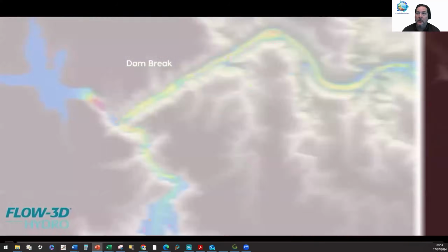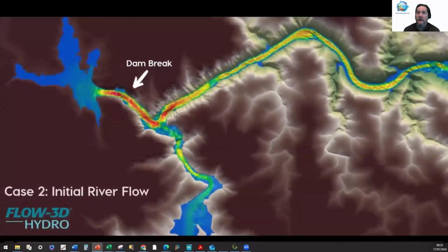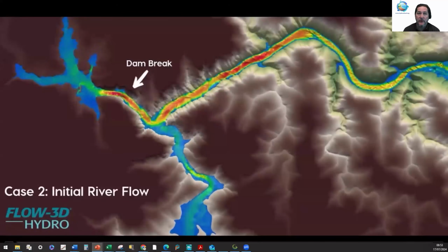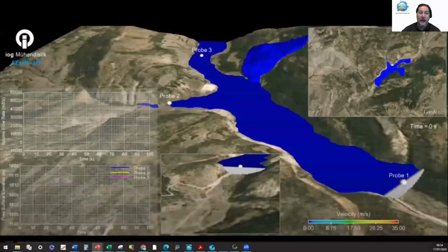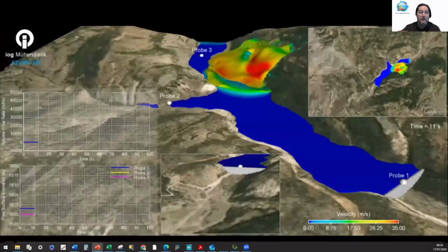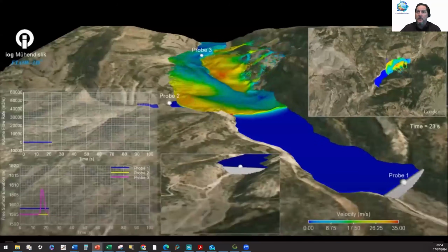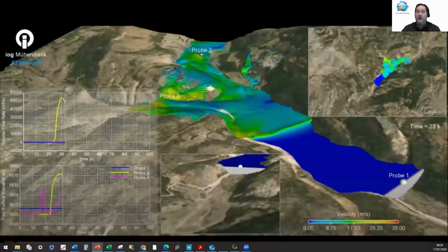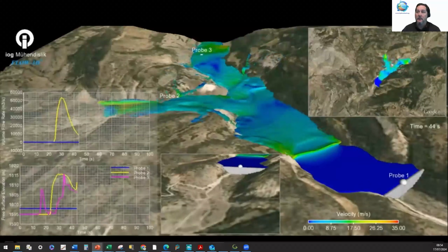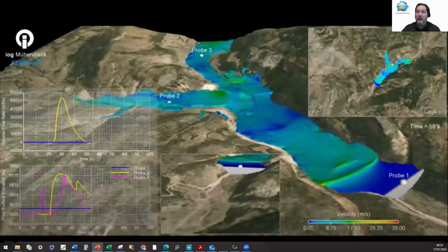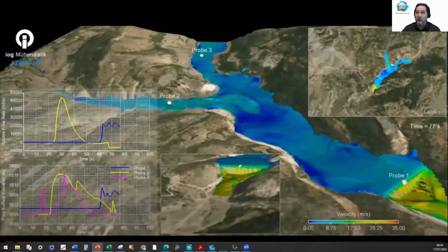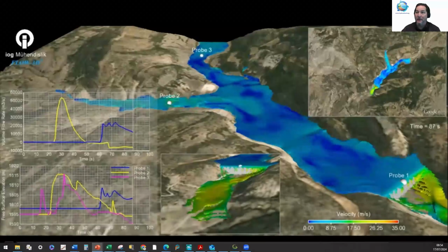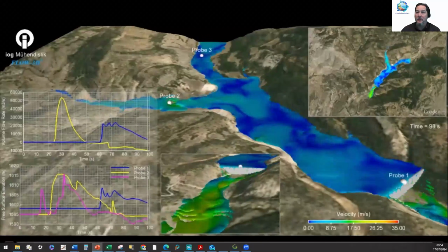So it's getting to be a little different than some of the previous advice, which you might still see published out there, saying, oh, you can only use 3D at the actual structure, and then you'll have to couple it with 1D or 2D anywhere beyond the immediate range of it. Computational power, software and hardware abilities have been increasing, and it is possible to run something larger in 3D. It takes a lot of resources to do it, and there are some limitations.